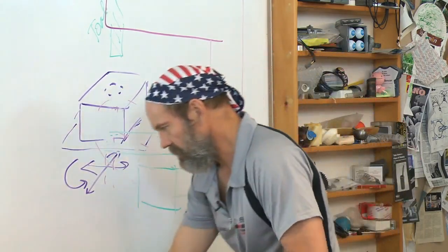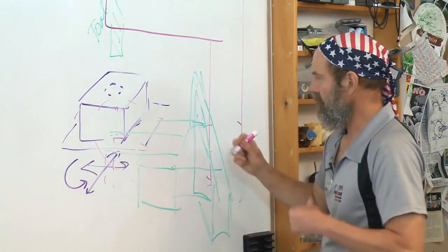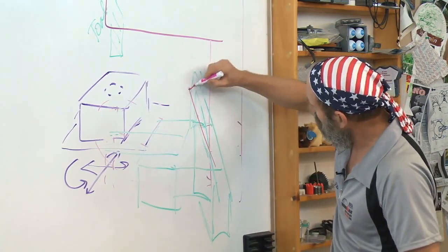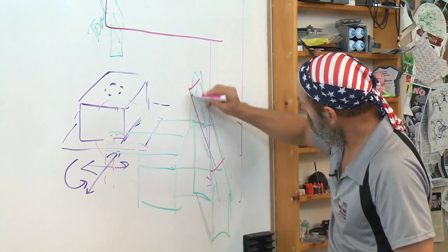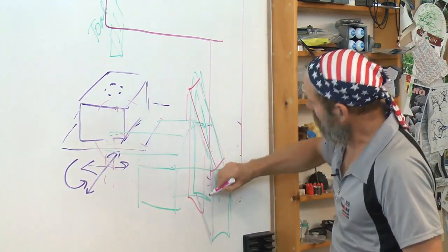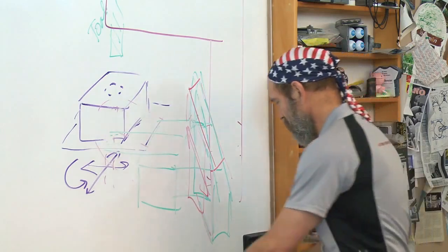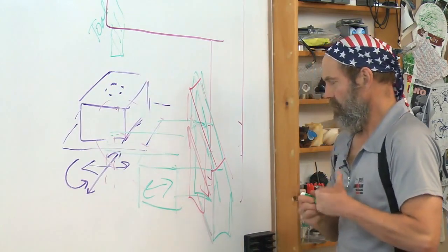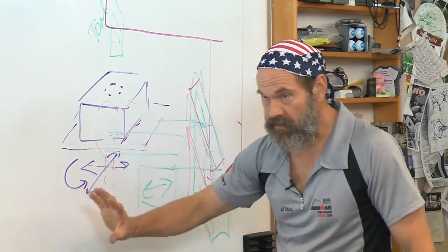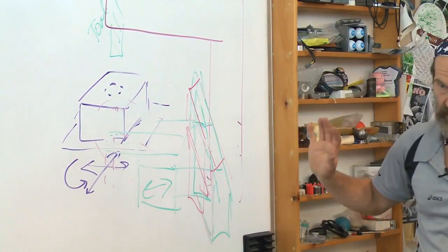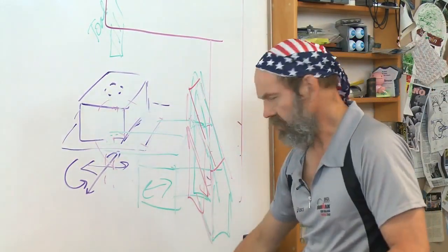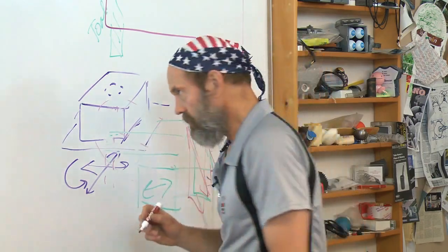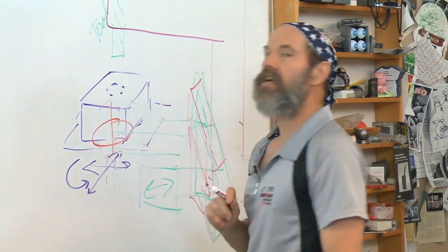And let me use a different color so you can see what we're talking about. I now have this first slide that moves in and out, and then back and forth I will draw a sketch for an axis that moves that way. Right? So my green axis moves in and out. The green axis is moving my part in and out, and the pink axis is moving back and forth. Now, I still got to rotate my part, so I'm going to put an axis at the end.